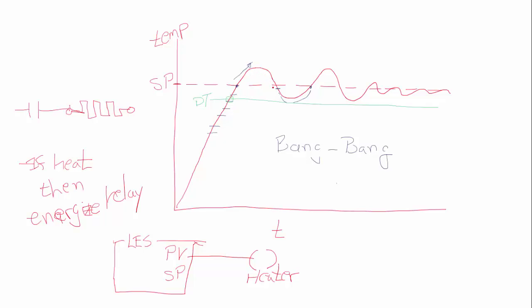But then I won't turn it on again until I get to here. So this is dead time. In these areas, I have no control whatsoever. Now this is not a very good example of dead time, but I hope it shows that within a dead time, you can choose when you are not doing control to prevent chattering, to prevent relays from making and breaking inconsistently.